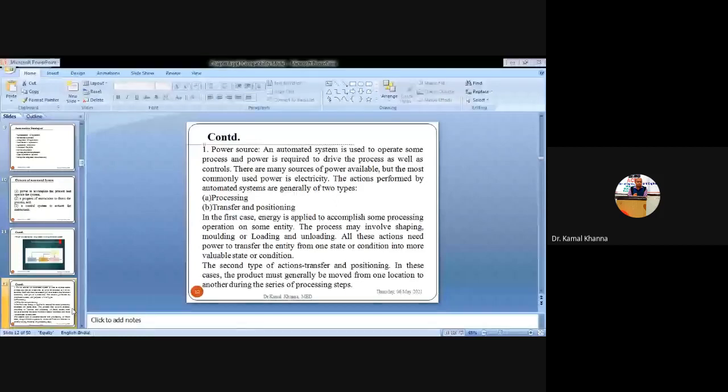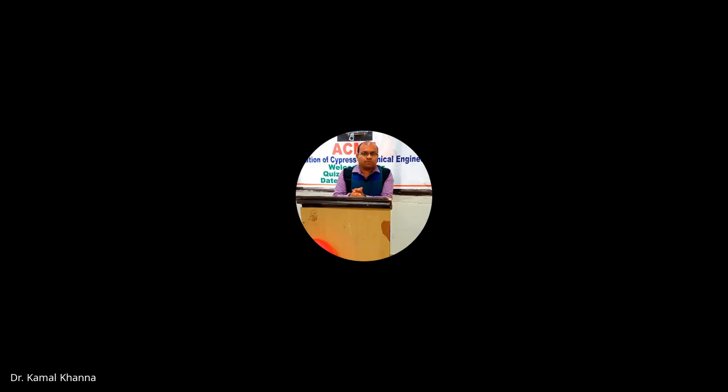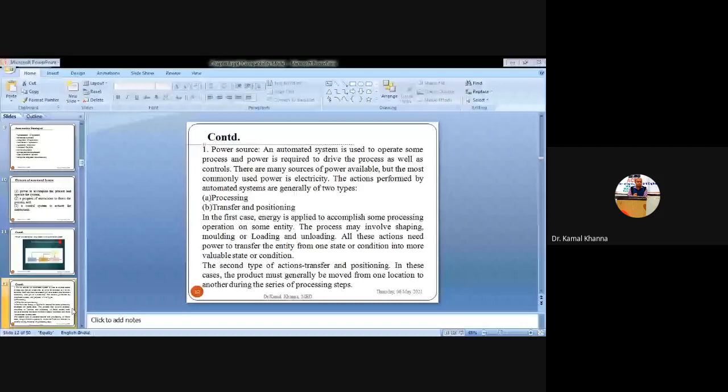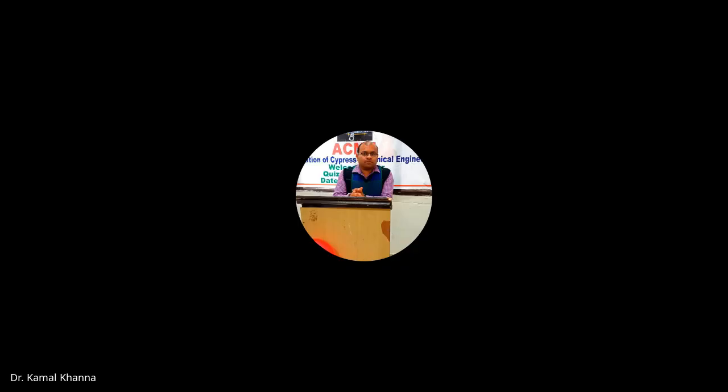and positioning. While you are setting the position, or setting the cutting conditions, or positioning any specimen, if you are dealing with the milling machine or the drilling machine, you are setting the workpiece table. And if you are performing the operation on lathe machines like the turning operation, then you have to fetch the tool from the tool library and perform the particular kind of operations.